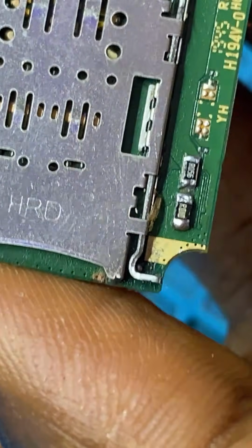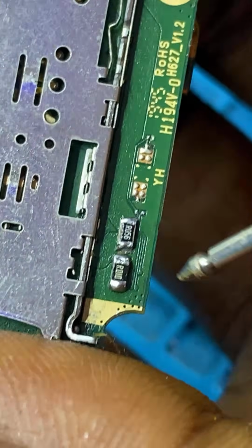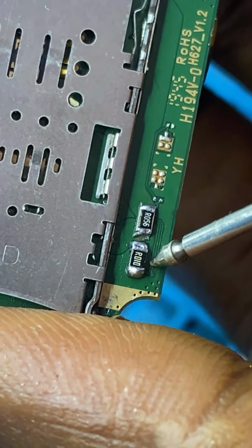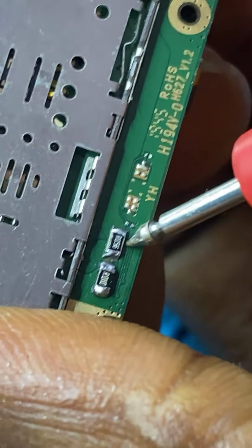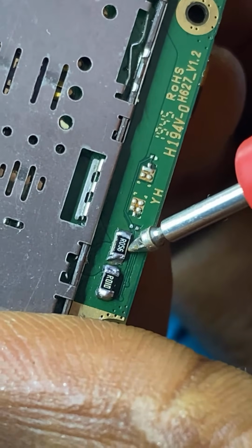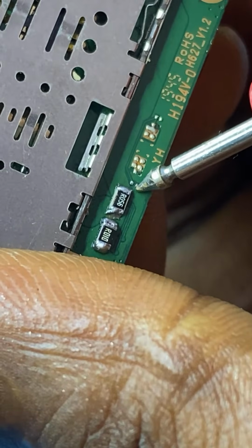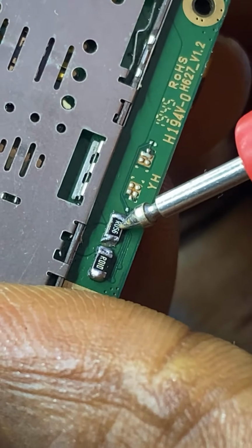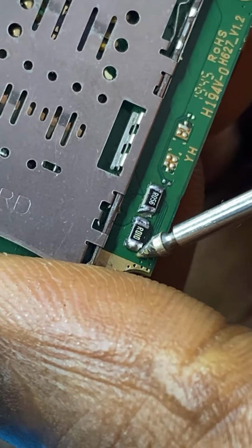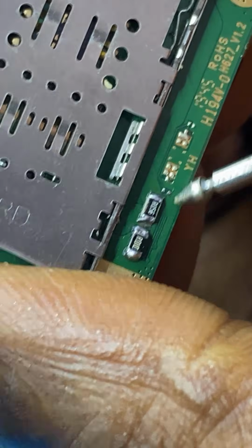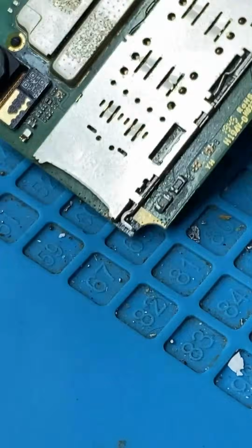So first thing, we have two fuse resistors here. I don't know which one is the problem. We have two. One is for the negative, which is the ground, and one is for the positive. What I'm going to do right now is first of all short the positive, because the positive handles a lot of power, you understand. If I short the positive and it's not working, I'll also short the negative. Let's be sure that the two fuse resistors are working before I proceed to fix any other thing on this PCB. So let me do that right now.